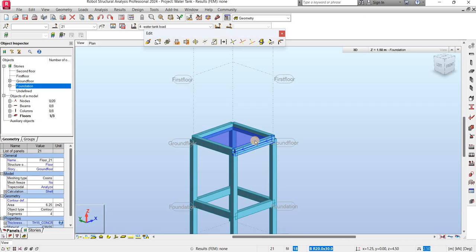So we're now going to divide force all over area to get the pressure in kilonewton per meter square, which will be the unit of load we'll be using to apply the load. So dividing 49.05 kilonewton by 6 meters gives us approximately 8.18 kilonewton per meter square.